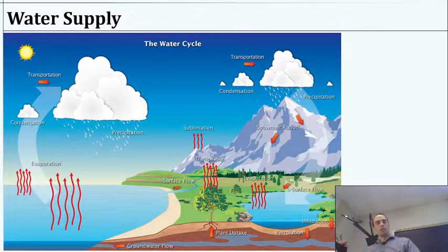But there is saltwater intrusion if we draw down too much of our water here, so there are ongoing battles lately about people trying to get industry to say, hey, just take from the Mississippi and treat it. It's going to cost you a little more, but that's going to preserve the groundwater we'd like to drink, right? That's a current tension because they're concerned about that salt water coming through. There's a couple spots in the barrier where it can come through, and it is because we're drawing down the water.